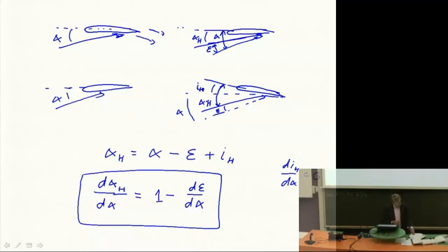And therefore we use the picture, it's also in your handout on page 5. We have to look at the complete configuration, so we take the horizontal tail, we have a lift of the wing, L, we have a lift of the horizontal tail, LH, and we have the weight in the center of gravity. Let's draw it in the middle between the two wings.